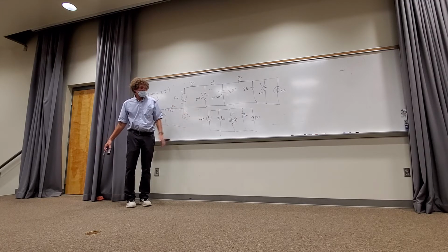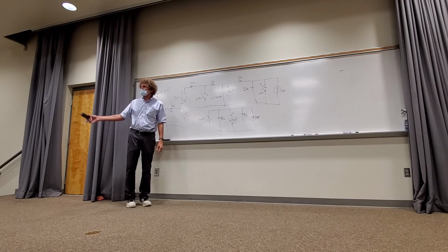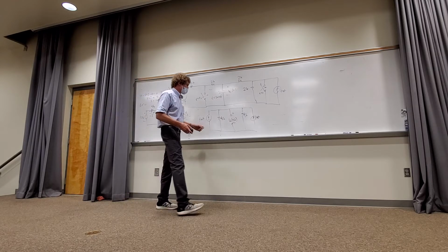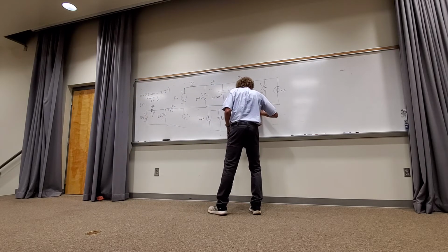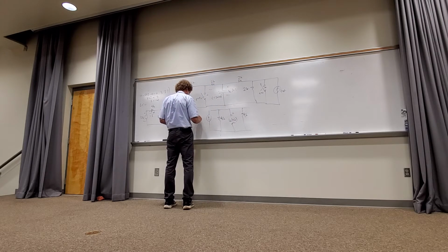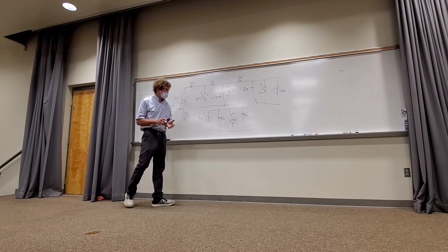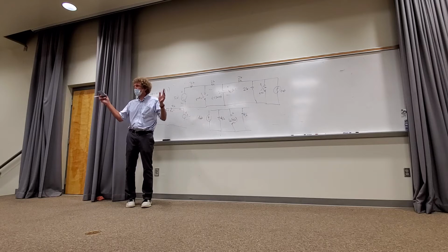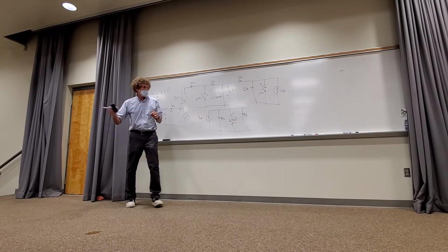What about the 3 milliamp and 1 milliamp? What can I do with those two current sources, anyone? Add them up to 4, right? Y'all agree with that, class? Sure. I'm just going to put 4 over there. What about the 4K in parallel with 4K? Aren't they in parallel? Let me do it that way. So what do I replace them with, class? 2K, sure.